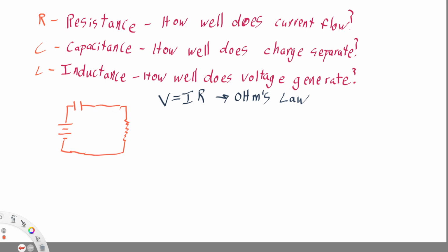Dallin, how is that different from a battery or the voltage source? Can you be more specific? We said the capacitor basically is like a dam that builds up the charge, but the voltage source already has a charge and it's releasing it along the wire until it hits the dam. Yes. And the charge will continue to build up on our capacitor, on this dam, until the voltage across the capacitor is the same as the voltage across your source.